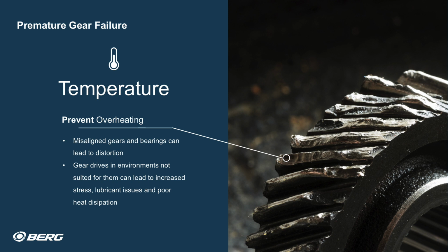Going back to the application constraints, it is critical to identify as much as possible regarding the operating environment of the gearbox. Items such as motor fans and other sources of air movement can significantly help performance. However, some common polymeric coatings that can give significant corrosion protection can also act as a blanket and restrict the flow of heat. Review this information and the results of this carefully. It will be of critical importance.